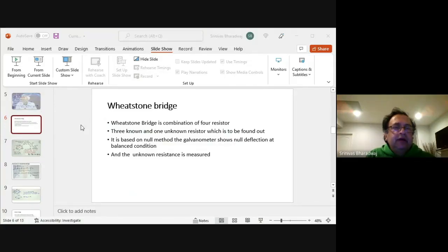This particular ammeter is like an open. There is no current through it. Now, why is that? Why is there no current through it? I1 R1 equals I2 R2. If I1 R1 equals I2 R2, then what can you say?